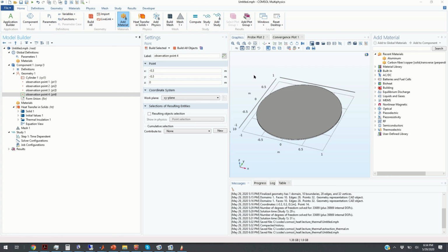The next step is to define the regions at which microheaters are acting. Now, we can model microheaters as points, or we can model them as regions. If we model them as points, we will most likely end up with certain singularities in our model. The better option is to model heaters as regions. So we are going to define a region, for example, a circle, and we are going to assume that at that surface or at that circle, we will have certain power acting on.